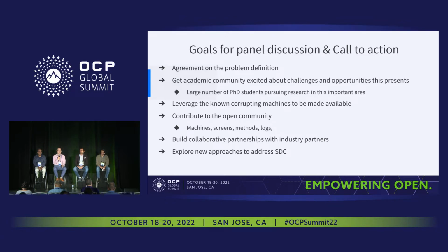And then a second piece of the problem, I think, is that when you're talking about silicon defects, you have time zero defects, you have latent defects, and that's always been true. And so even if coming out of your semiconductor manufacturing environment, you had zero defects and we'd managed to solve the problem completely, you'd still have latent defects. So you have to have the ability to maintain the semiconductor over its lifetime. And so the idea that semiconductors are maintenance-free and perfect is an idea of the past.